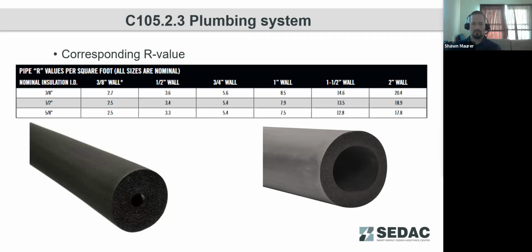For steam lines and chilled water lines, those insulation values are in mechanical design manuals and will be thicker. You'll see things more like fiberglass insulation on those with a protective wrap, and not so much these foam sealants or foam insulation.